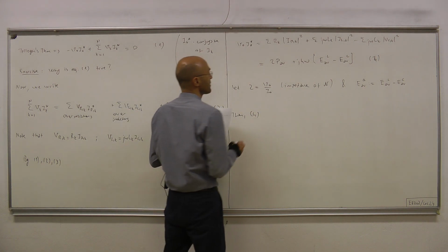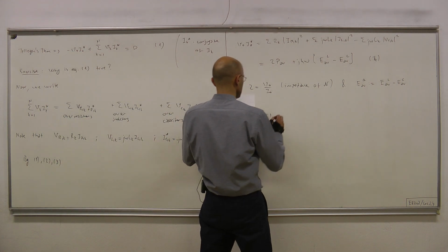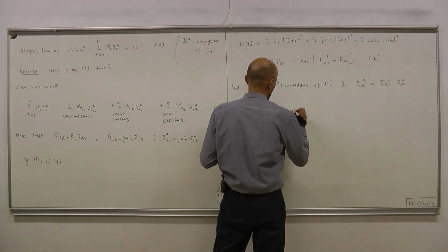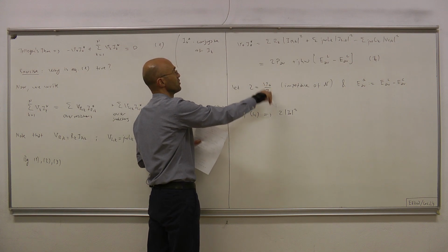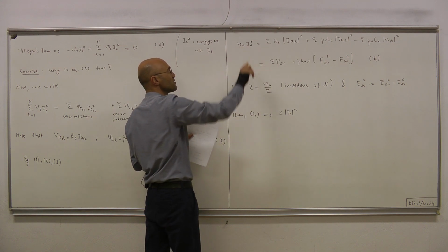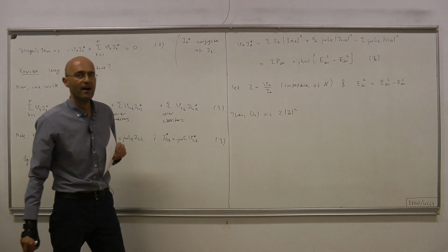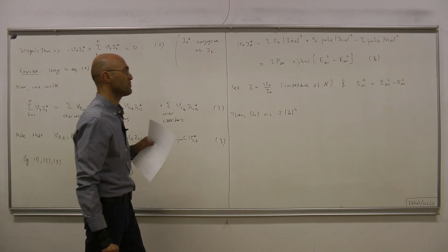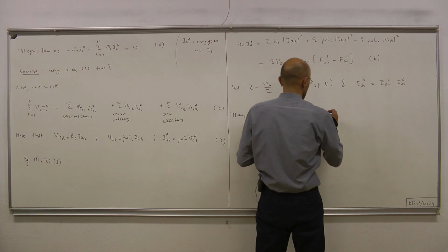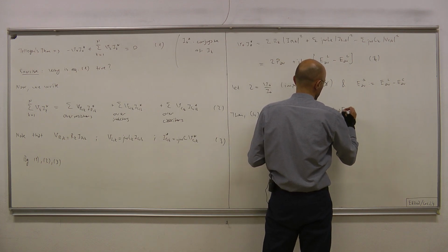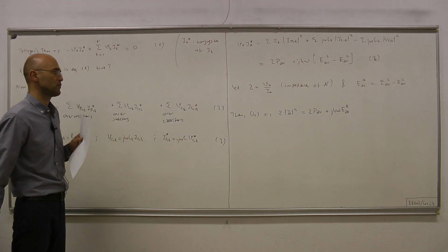Then the last equation that we obtained, equation 4, implies Z times I0 magnitude square. Now V0 is Z times I0, so therefore this is Z times I0 conjugate. I0 conjugate will produce magnitude square, and we have for the left hand side Z times I0 square, and that equals 2P average plus j4 omega E average delta. Okay, the difference of stored energies.